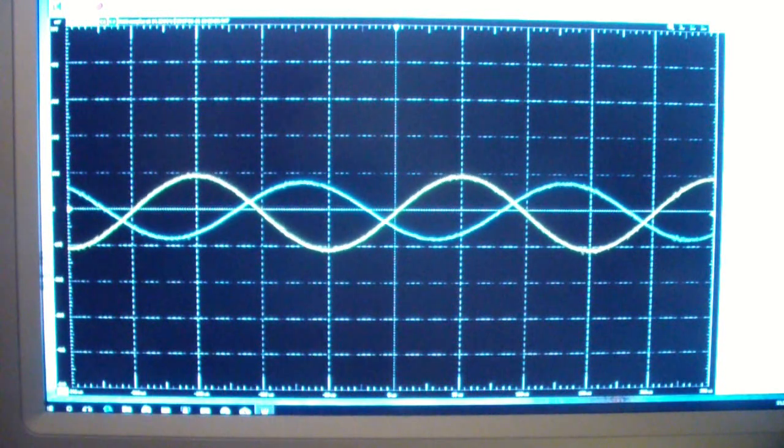Well, for one thing, we have a working circuit. It has a gain of about 10. It is biased about where we thought it would be. But the most important thing to learn about this is that you can design transistor circuits, at least to a first approximation, with nothing more than Ohm's law.